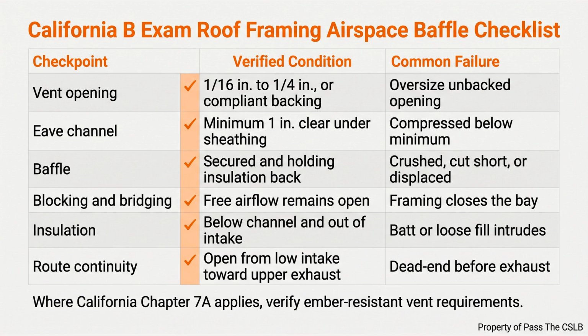I keep two controls separate in my mind. Air sealing limits the amount of warm interior air and vapor entering through leaks. Ventilation gives moisture and heat in a vented attic a path out. One does not excuse poor execution of the other.